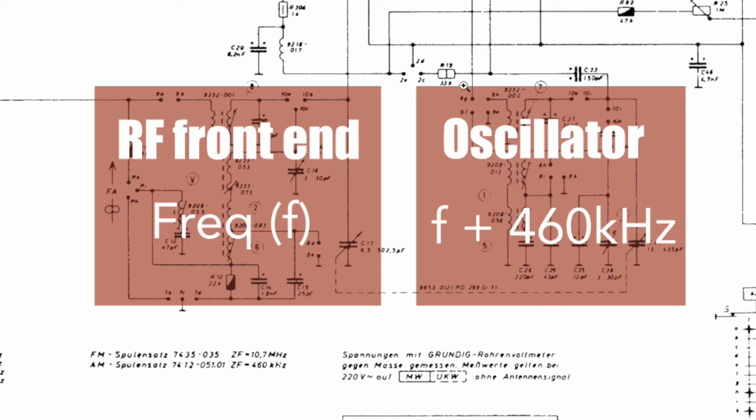So when you tune the front end and the oscillator, you do that by placing the dial on a known part of the dial plate on the display, and then you adjust your oscillator. You don't adjust that one first, you adjust your oscillator to bring that signal into the position of the dial that you've selected. So you adjust it slightly. Usually it's not too far off, sometimes it's not off at all, but you adjust it so that the particular frequency you're looking at is exactly where you expect it to be.